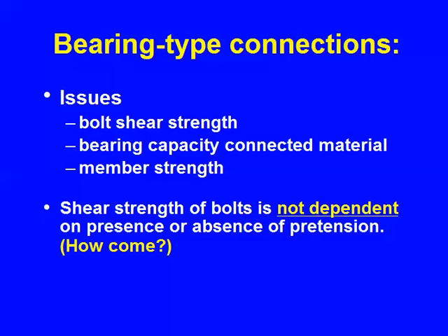So this group over here, they pre-tensioned their bolts. That group over there did not pre-tension the bolts. The majority in the middle didn't know what to do. They're going to await the outcome. And the answer is, I'll have to show you why, it doesn't matter whether this group pre-tensioned and that group didn't pre-tension. The shear strength of the bolt is going to be the same. Okay?